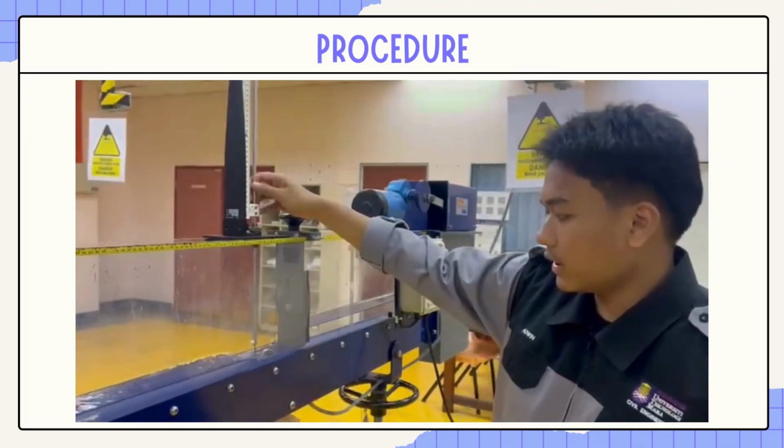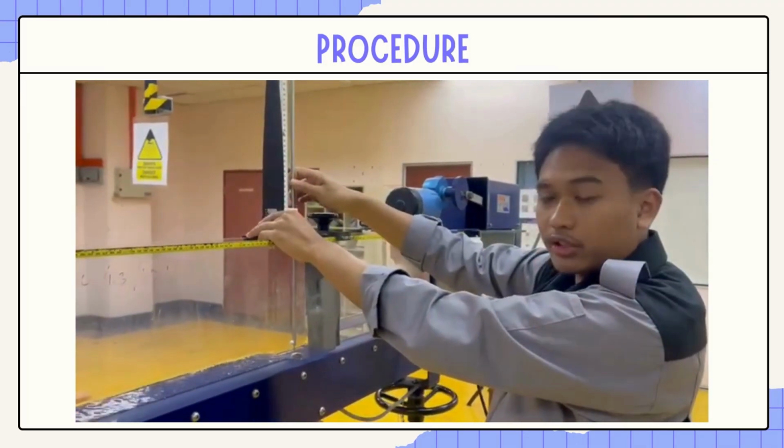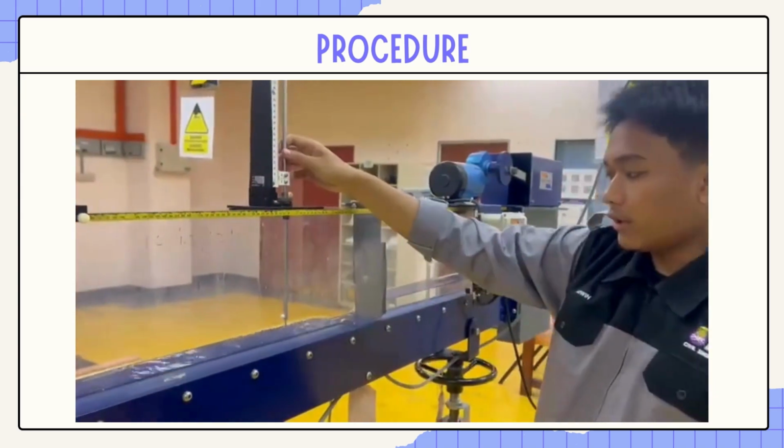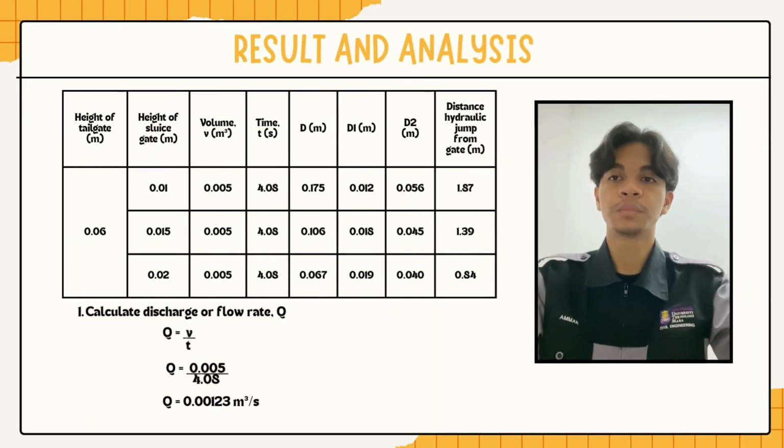So for the next step, we measure the height of the downstream using this point gauge, and we measure the upstream using the same point gauge. Upstream height, and we record the data. We move on to the next part, result analysis.